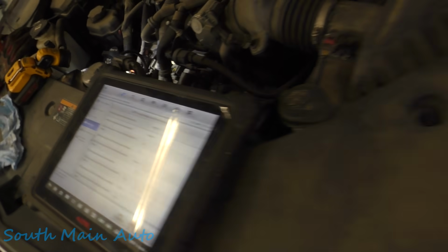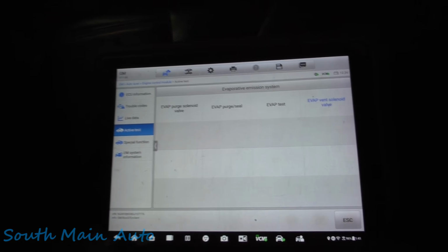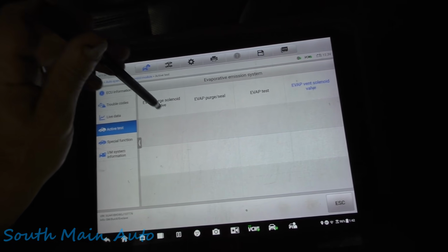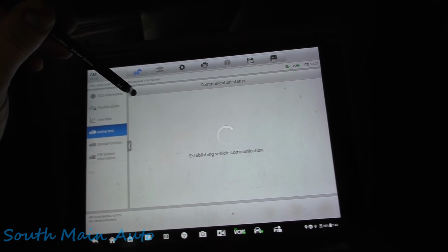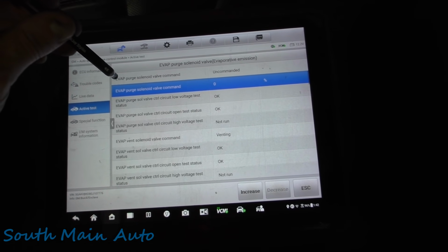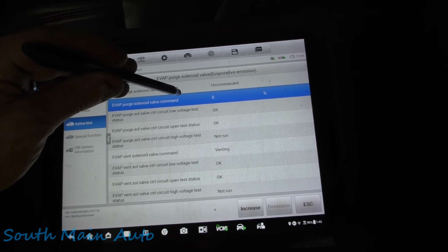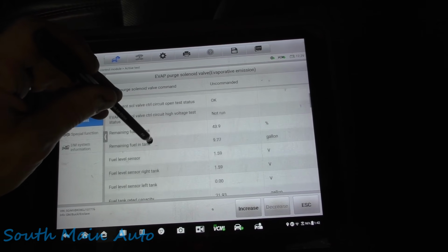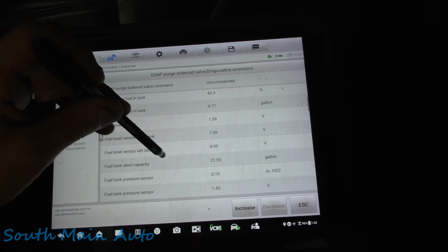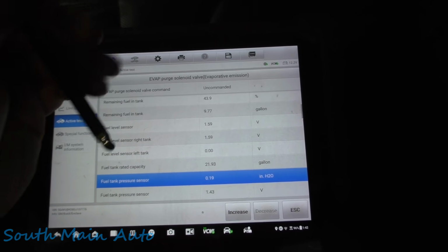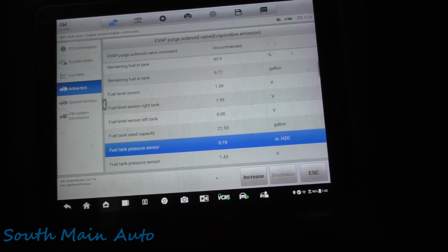Stand by, folks. It's gonna be noisy out there because the coolant sensor is unplugged. I got the engine off right now. We're gonna go to purge valve. I think we just have a bad purge valve, which wouldn't surprise me. We're going to keep it commanded at 0%. And then we're going to look at tank pressure. That should not change. Okay, so let's go ahead and start it.